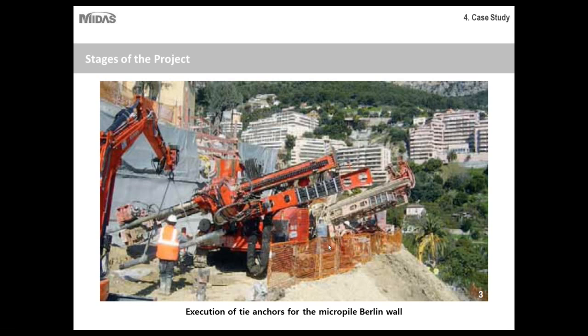So it is still under construction, and because of the steepness and the height of the structure, they adopted staggered retaining wall construction so that they can erect the wall and mount the equipment, and then do the excavation further, and then move down in a step formation.